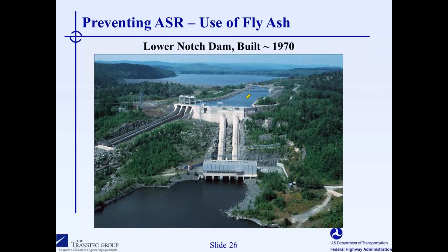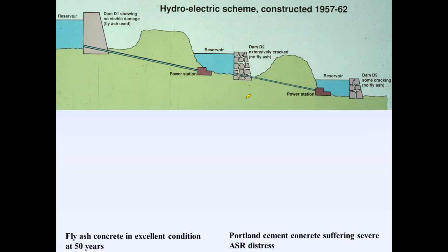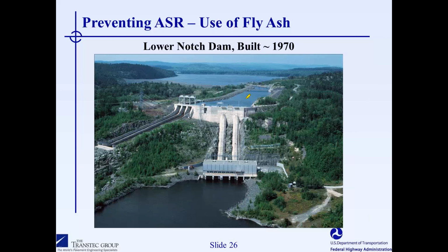They did know this aggregate was reactive. A lot of the existing structures in the neighborhood were showing severe signs of alkali silica reaction when this structure was built. So they were well aware of the problems with alkali silica reaction at the time of construction.